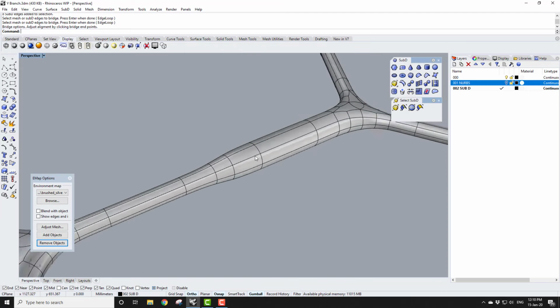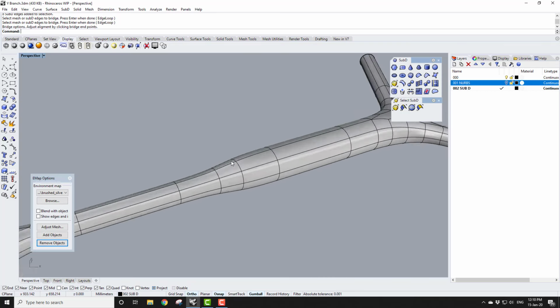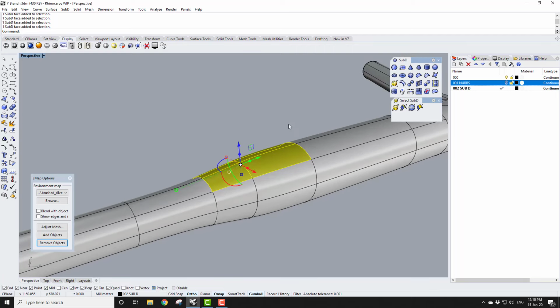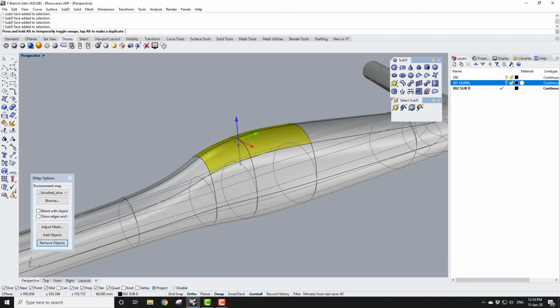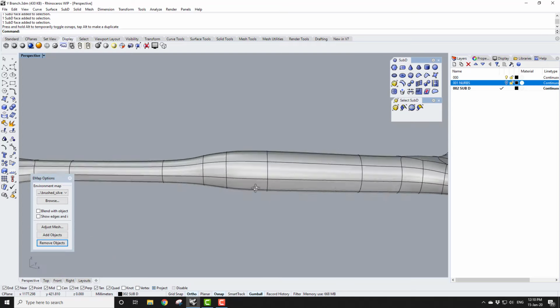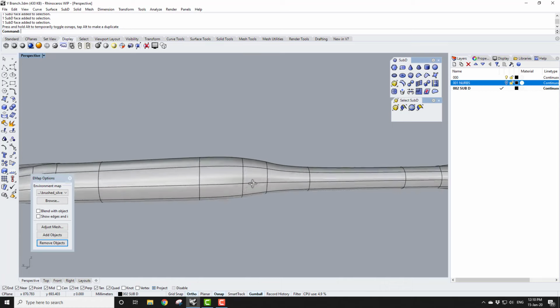And again, the big advantage here of SubD is this whole object here is treated as one curvature continuous surface. So if I want to adjust the shape locally, for example, to make this asymmetric, let's say I want to push this area upwards here, I can do this. Okay, and I don't have to worry at all about the smoothness here.